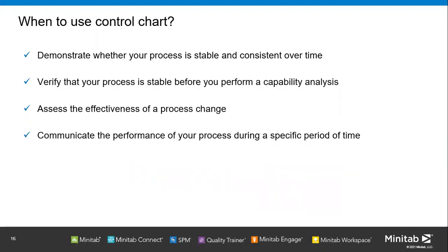Okay, so the control chart is used in two different phases. The first phase is to assess the stability and to find an acceptable estimate of the process parameters. If you Google why people fail to implement SPC, they fail to decide what the process parameters are in their process. So how do you get the parameters of your process? Maybe you can go for the FMEA, so you can get the parameters of your process. You have your process, and as an SME for that process, you need to know what your quality characteristic is.